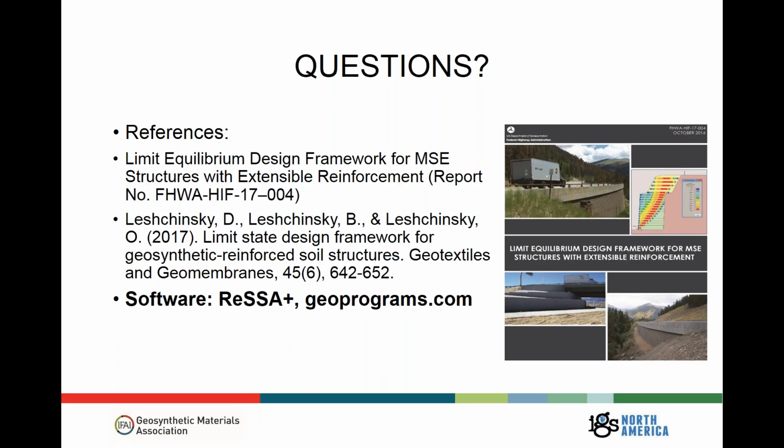So indeed, there might be some loads higher than you might design for, considering these serviceability conditions. However, we're often applying a series of safety factors and reduction factors to make sure we feel comfortable with the level of loading that we might see there.